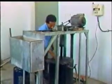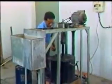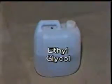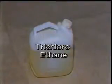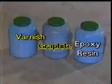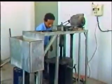First of all, a mica strip of a size depending upon the cutting die is coated with carbon resin. Carbon resin mix is prepared by stirring black pigment, ethyl glycol, trichloroethane and a hardener apart from other ingredients like varnish, graphite, epoxy resin, etc. for 24 hours or more.